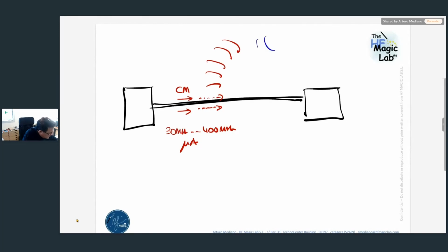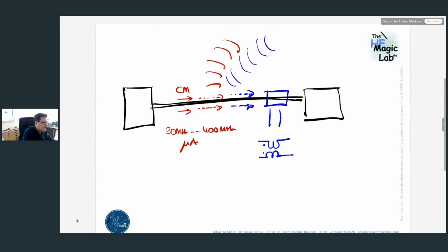It's the same if you are interested in immunity. You are receiving the electric field, and the electric field is inducing common mode currents in the cable. In this case, the idea is to introduce in the middle something that is a low pass filter. So you introduce a common mode choke because it's invisible for your signal, but it's introducing impedance at the frequency you want to remove. Remember, this is not a broadband filter, so you will only be focused on reducing the area, like you have seen in the demo, between 50 megahertz and around 200 megahertz. And that's all.